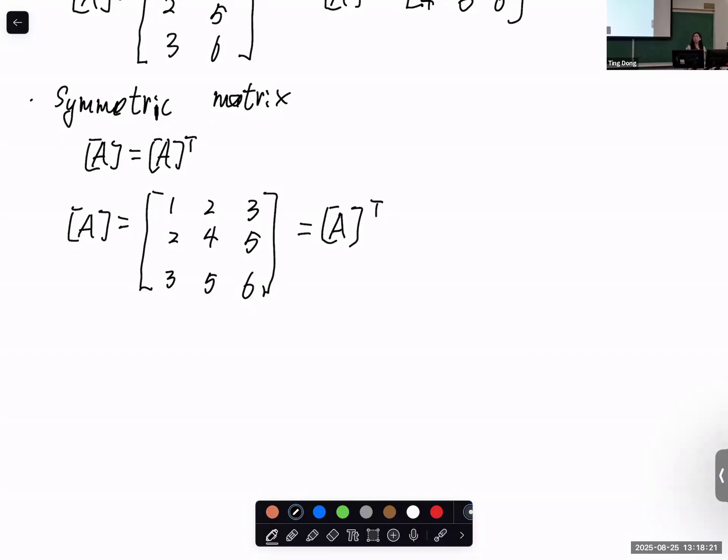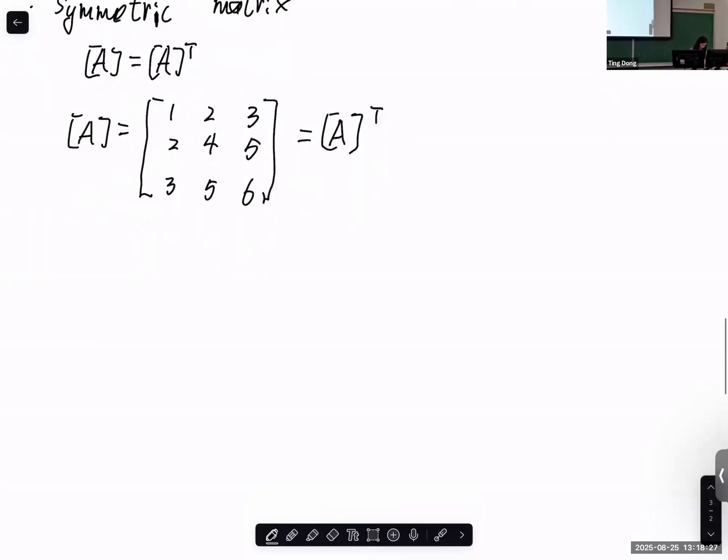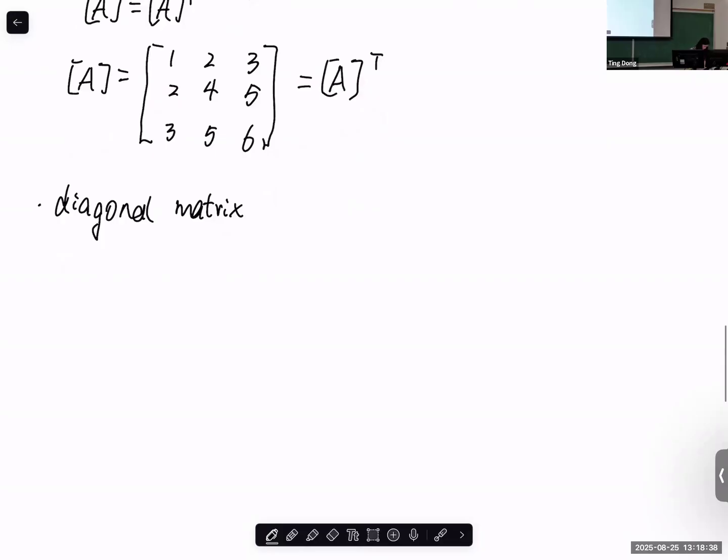So we used these things in our previous classes. All off-diagonal components become 0, or in solid mechanics, you can say all the shear stress components become 0, only normal stress is sustained, and those diagonal terms become the principal stresses.